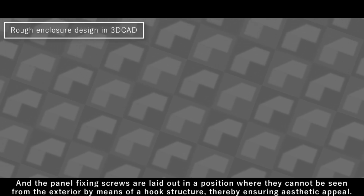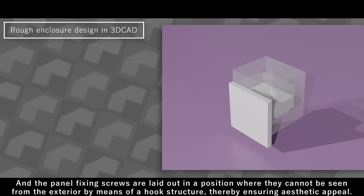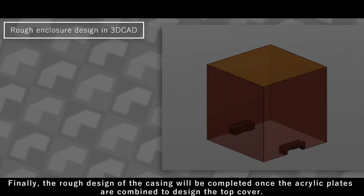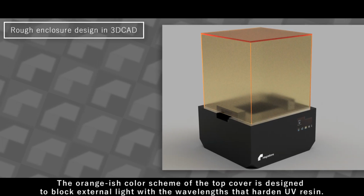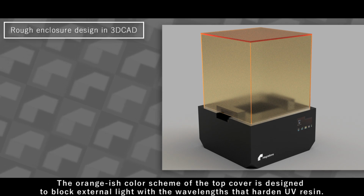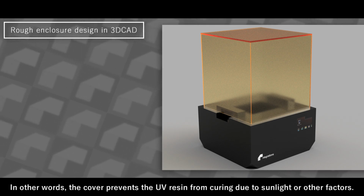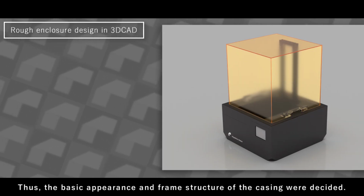And the panel fixing screws are laid out in a position where they cannot be seen from the exterior by means of a hooked structure, thereby ensuring aesthetic appeal. Finally, the rough design of the casing will be completed once the acrylic plates are combined to design the top cover. The orangish color scheme of the top cover is designed to block external light with the wavelengths that harden UV resin. In other words, the cover prevents the UV resin from curing due to sunlight or other factors. Thus, the basic appearance and frame structure of a casing were decided.